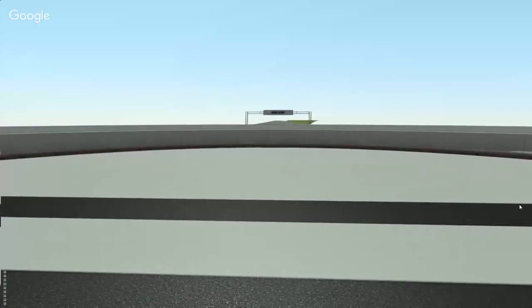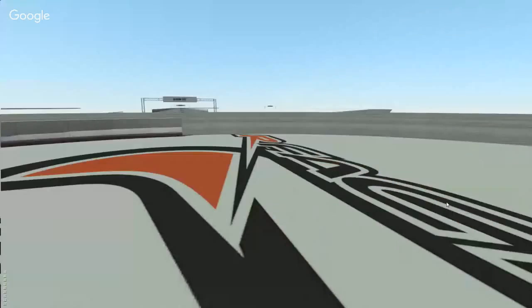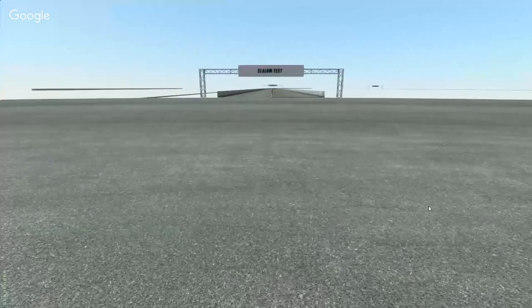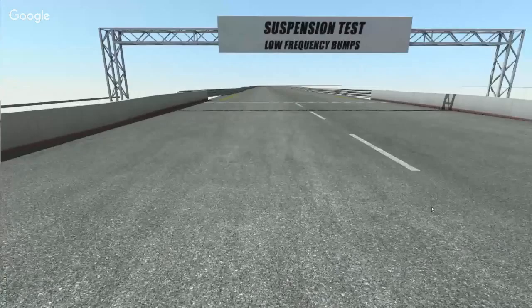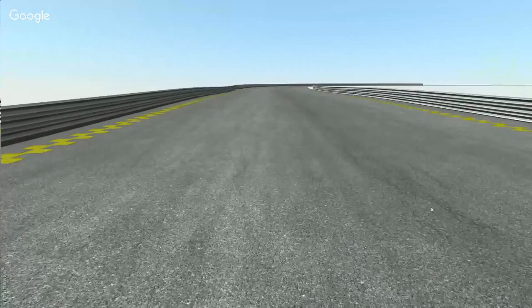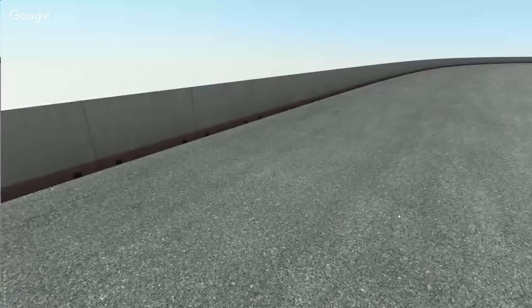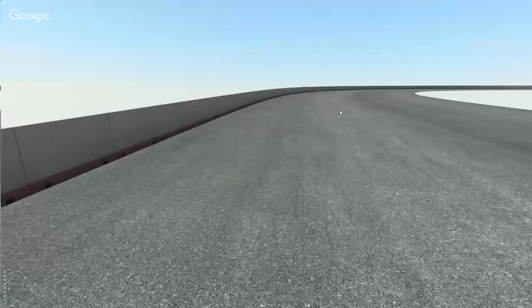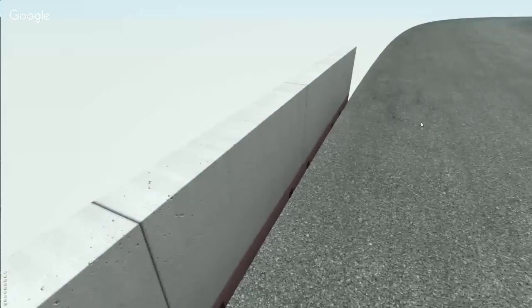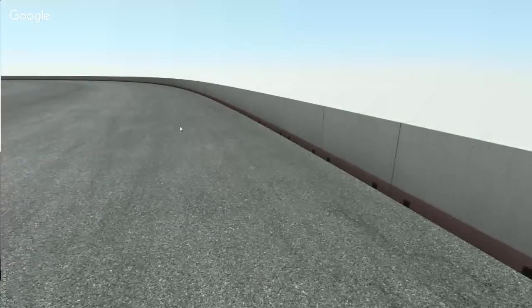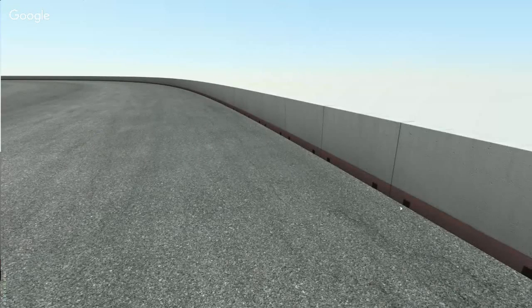And let's see how our wall works, how it will be looking. We made it over here. And here is our wall, which is bending nicely around the corner. And that was done with a basic straight mesh, edge spline and path deform modifier.